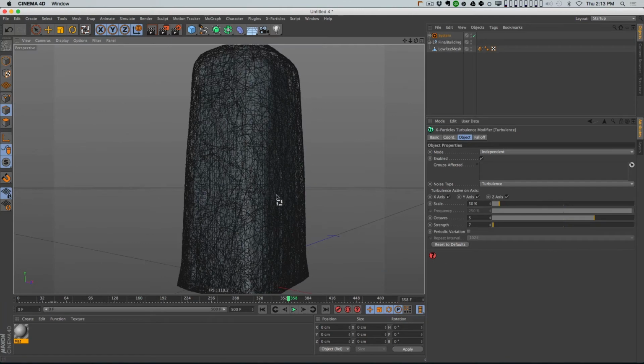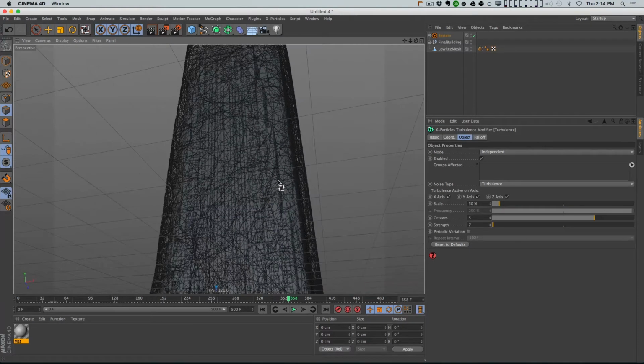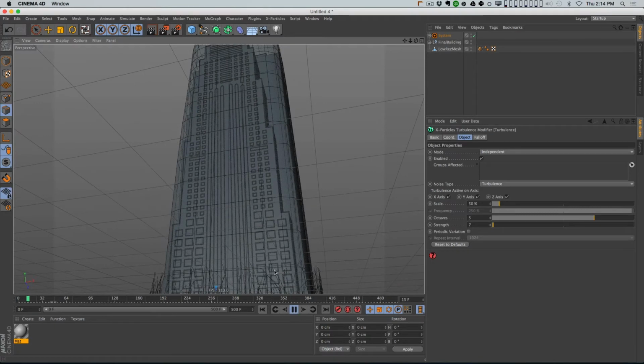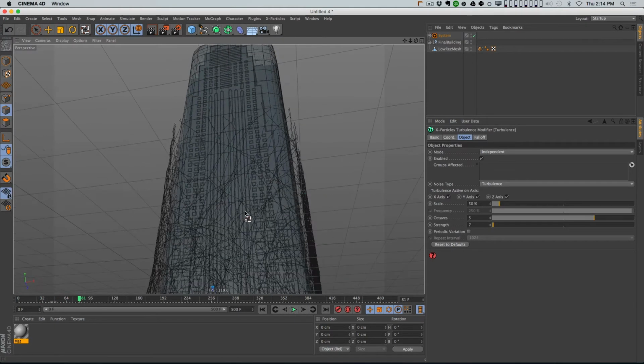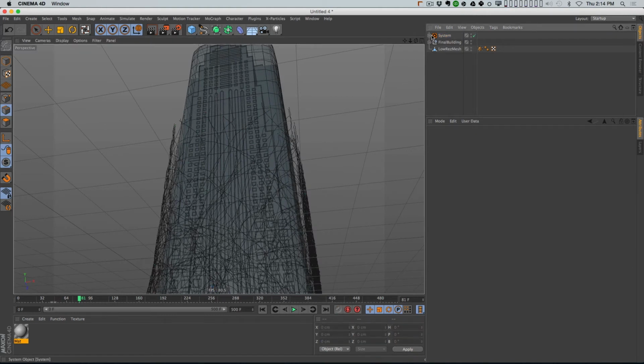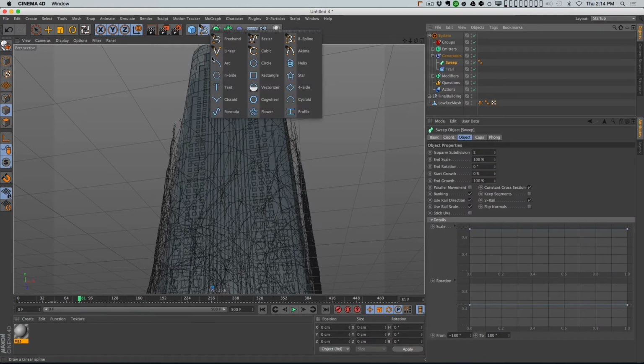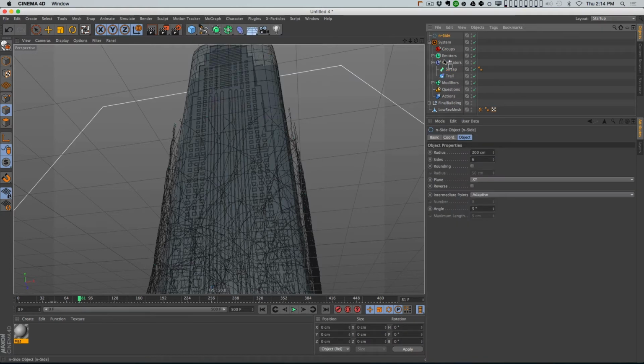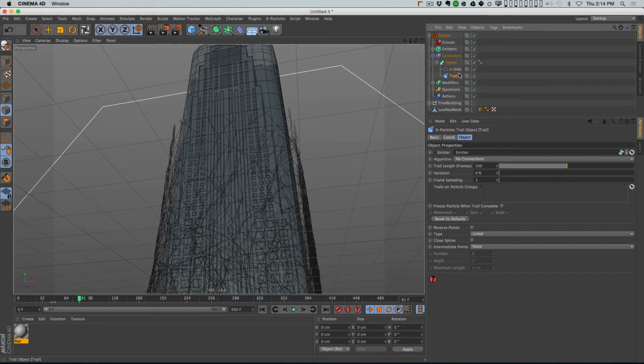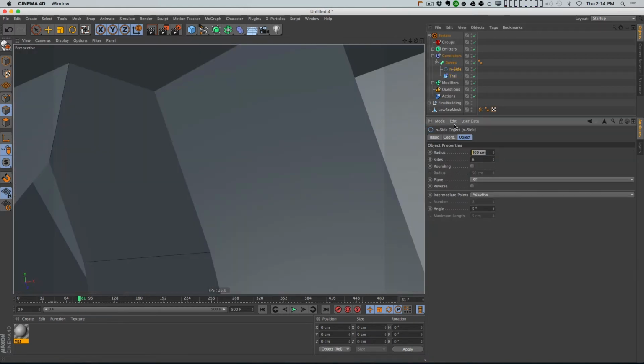All right, so here we are. We've got all these vines. Now, let me go ahead and put some geometry on this for a minute and show you one of the problems we are going to run into. All right, so here are some vines. And what I'm going to do is grab my trail object. I can just leave it in there, actually, and I'm going to add a sweep NURB to it. I'm going to add an inset spline, and I'm going to say sweep that inset spline through the trail, and we'll make this